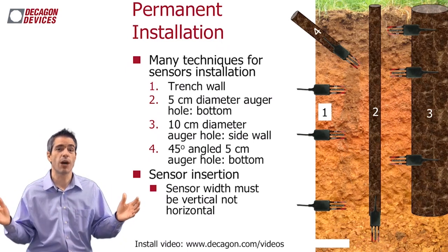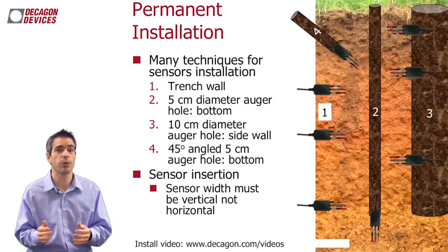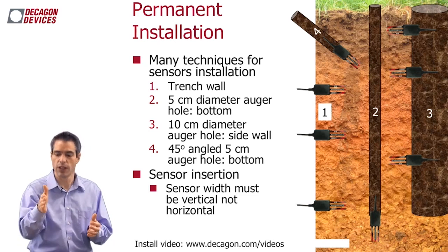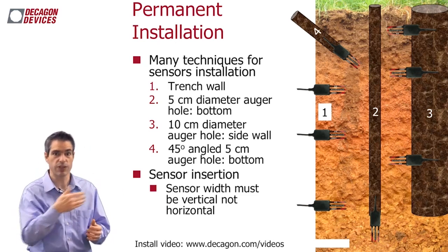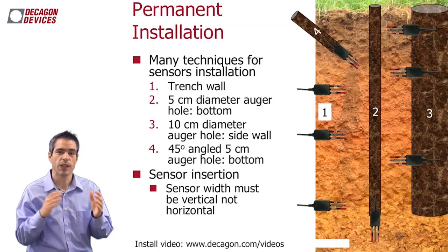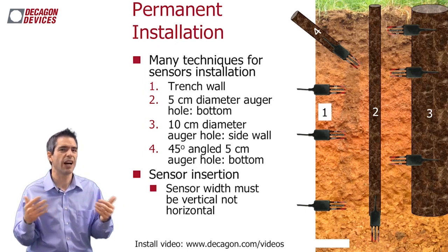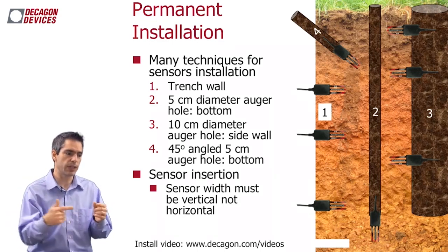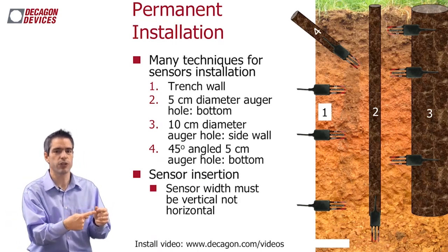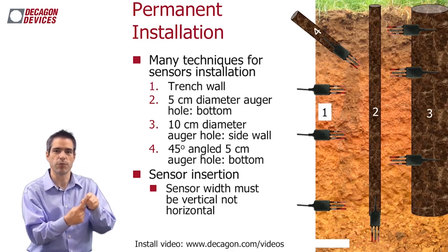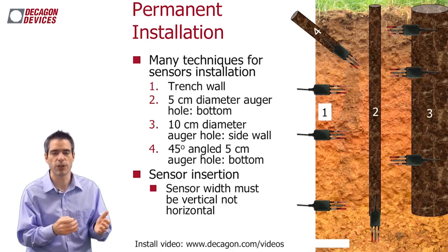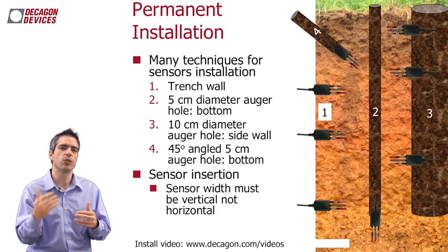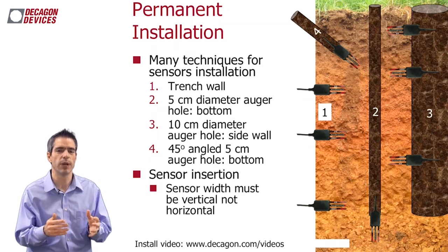First of all, one of the most common ways, and the way we did it back in the very beginning, we just dug a pit and stuck sensors carefully, vertically, like this, right into the pit wall. That's the first technique we used. But obviously there are some challenges with that technique. There's a lot of effort involved. Sometimes the cables that come out of your sensors horizontally and need to go vertically can break the strain relief and other things of your particular sensor. So there was a concern over that technique and we started working on other ways that might be better.